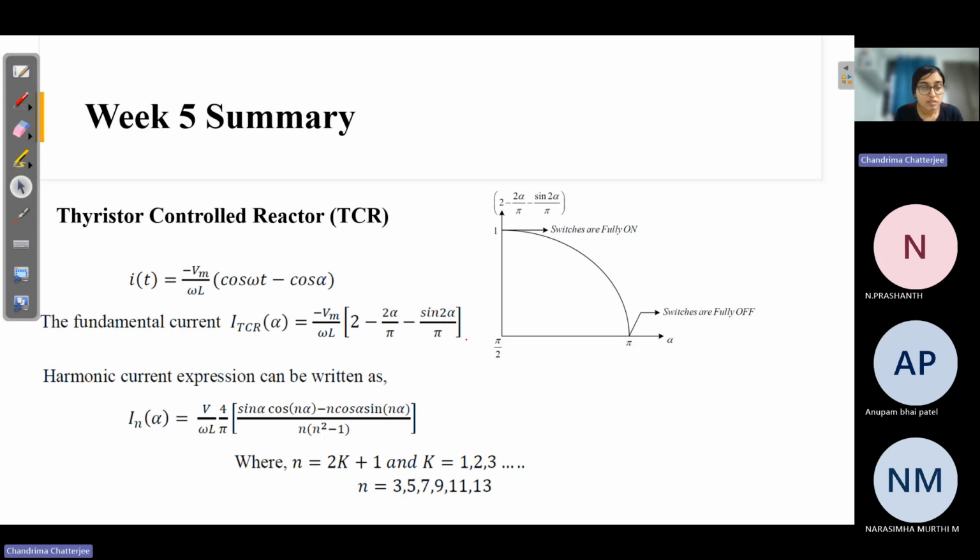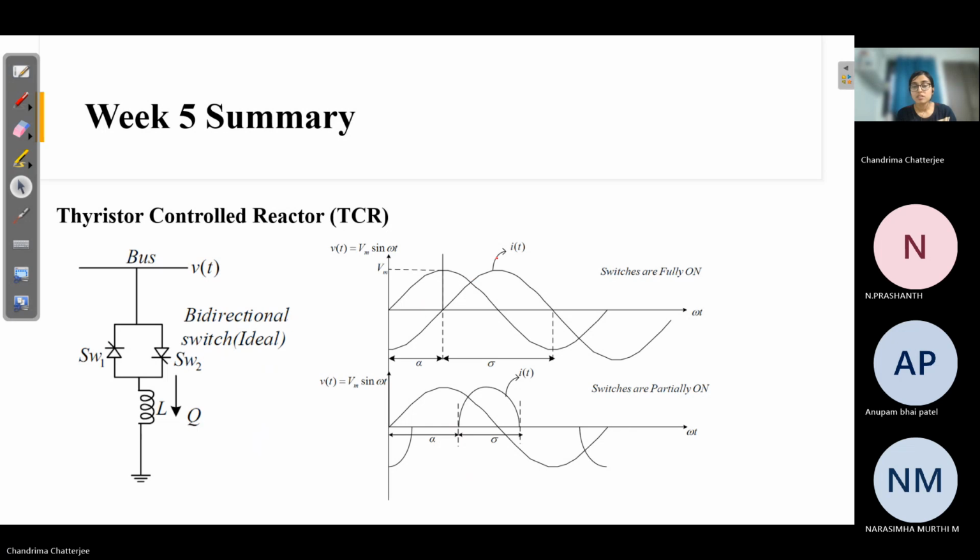Now, one thing here is that when the current is continuous like this, there is no problem. If the voltage is sinusoidal, the current will also be sinusoidal with some lag, lagging by 90 degrees for a pure inductor. But when the current is discontinuous like this, sometimes it is zero, sometimes it is there, in that case some harmonics will be introduced. You can understand that there will definitely be some harmonics.